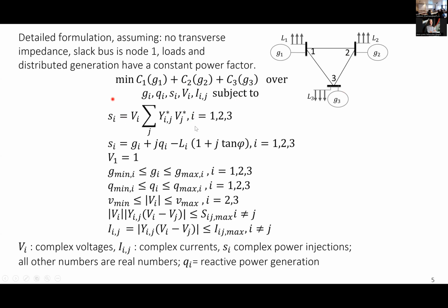Now, this is the grid, the load flow equations in rectangular coordinates, where the star means the complex conjugate. So this is expressing the injected power at bus 1, which is equal to the voltage at the bus, the complex voltage, times the conjugate of the current, and the Y is the admittance matrix of this grid here. So that gives the first equation.